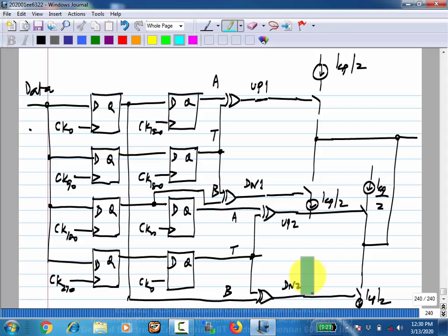So those things are there. Now what advantage does it have? The data is still running at this speed, but the clock is at half the rate. Okay. So again, it's not the same as running everything at half the rate. Then the latches will become better, the dynamic gain of the latch will be better, and so on.